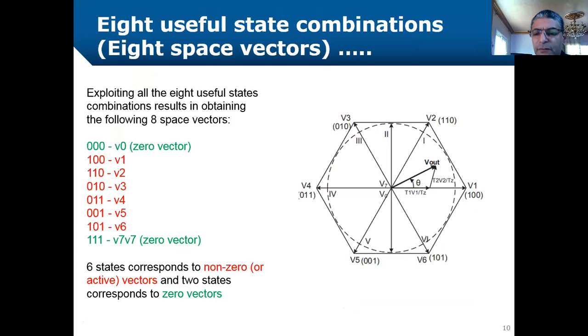So now we understand what this shape stands for. This is a hexagon, and the diagonals of the hexagon present the space vectors resulting from the different combinations of conduction states of each arm. These space vectors have magnitudes of VDC.